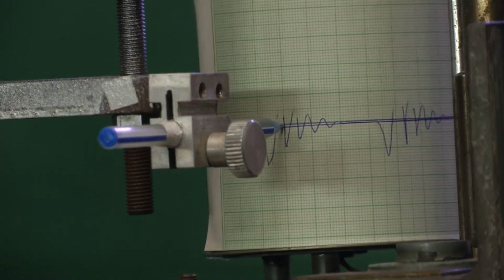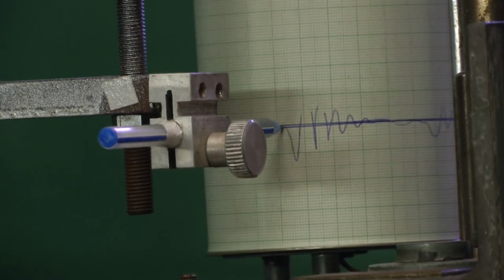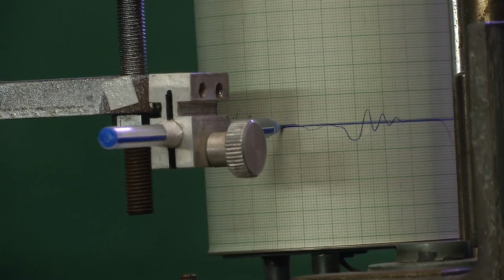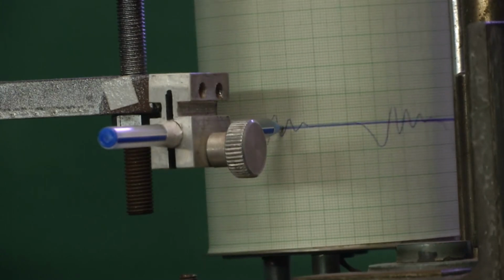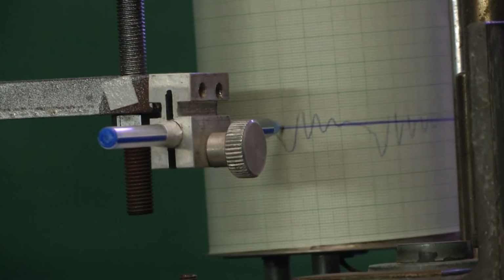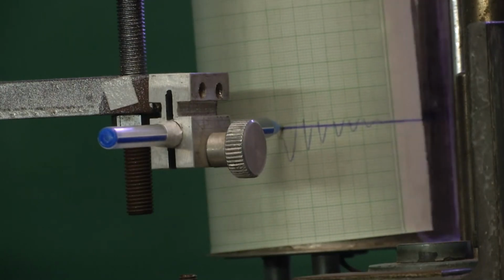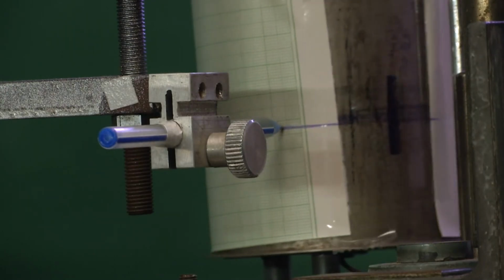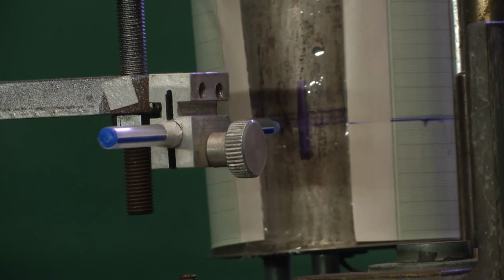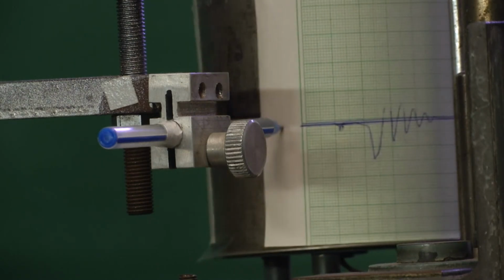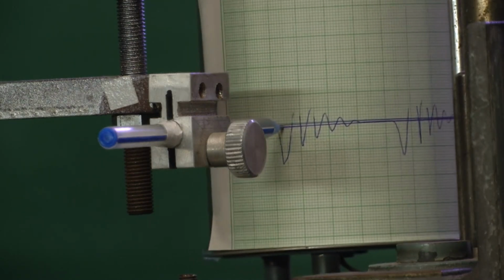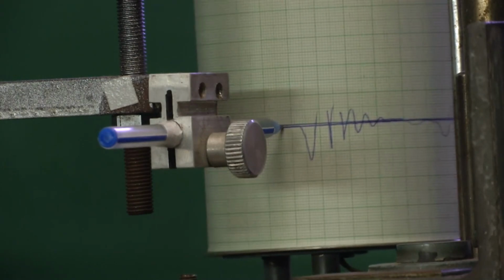So, we will provide you these graphical measurements traced out on the graph paper, and from that you have to find the amplitudes and take an appropriate number of cycles as is feasible from the short data, and then find out or calculate the value of zeta, the equivalent viscous damping factor.